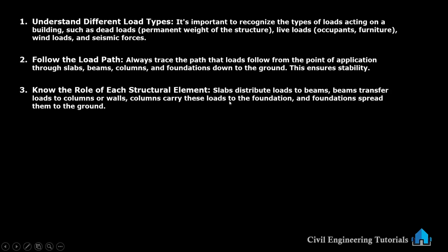From slab, load goes to beam. Then from beam, load goes to column or wall. Column or wall transfers the load to the foundation, and the foundation transfers the load to the ground.